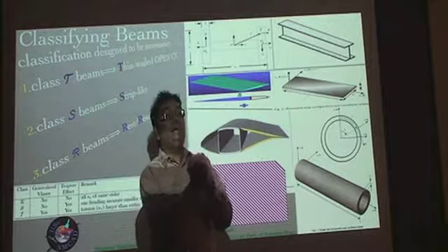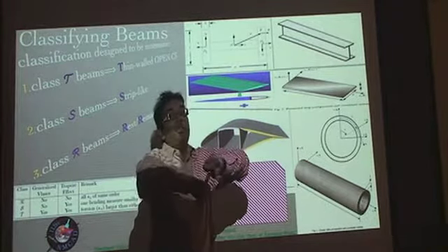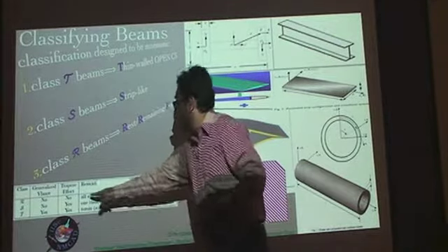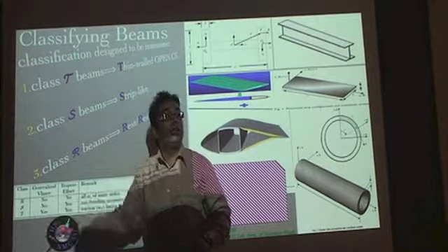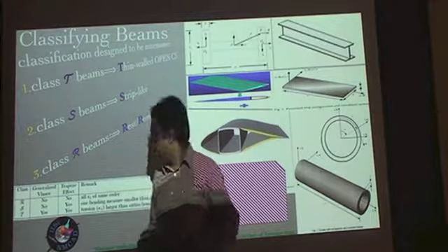So basically, the curvatures that you can get in terms of bending curvatures or the twist per unit length, which is also a kind of curvature, will all be of the same order of magnitude. So because of that, you see that there is no effect which is coming either from Vlasov or restrained warping or the nonlinear effects.